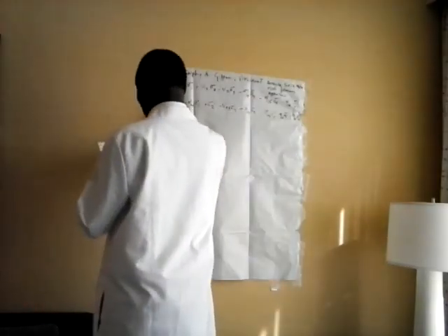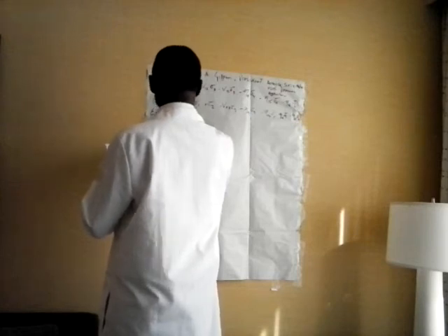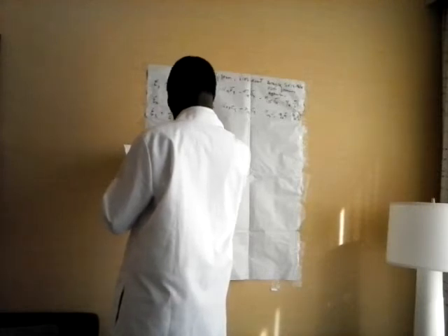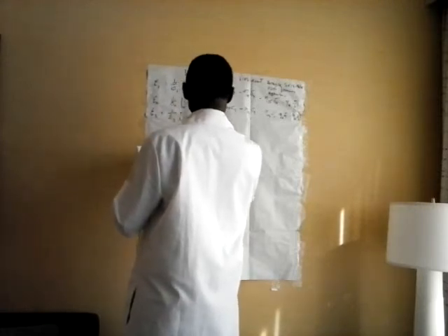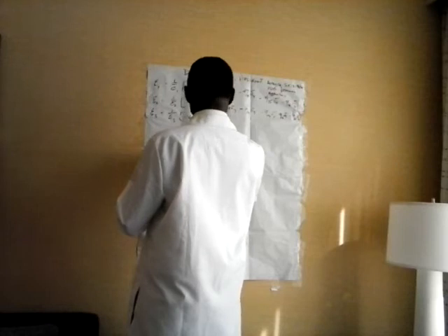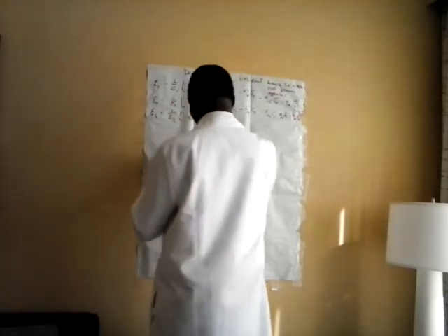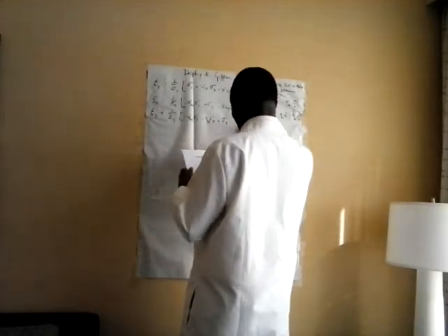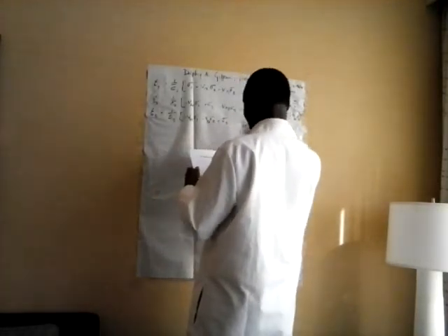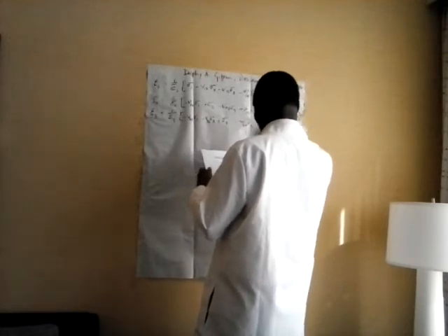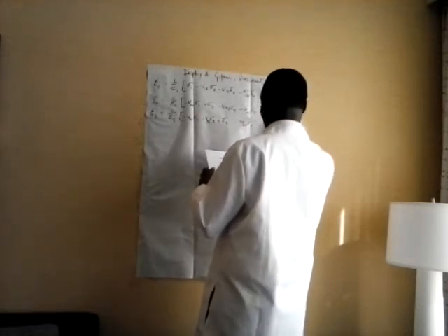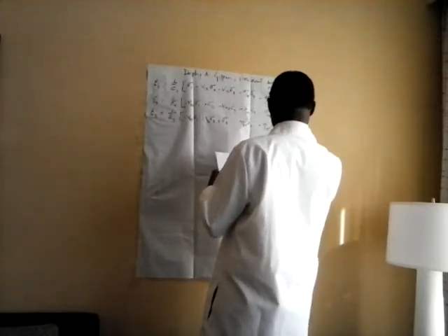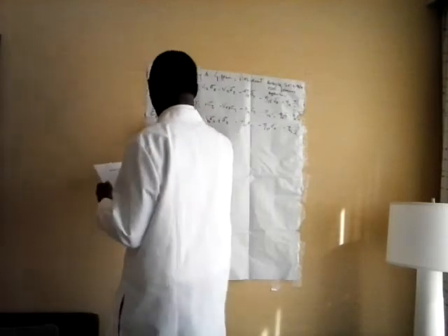Epsilon 3 is equal now to 1 over E3 times minus V31 sigma 1 minus V32 sigma 2 plus sigma 3 minus V34 sigma 4 minus V35 sigma 5.